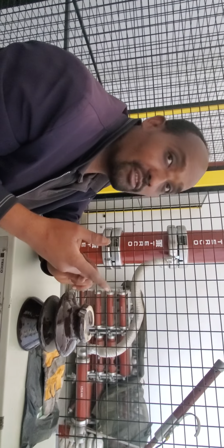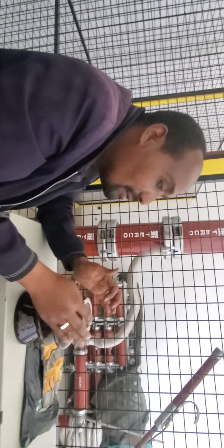Yeah. This implies that there is what? A breakdown of this solid device. That voltage is called puncture voltage. If you compare flashover voltage with puncture voltage, puncture voltage is much greater than flashover voltage. Flashover means breakdown of the air around this. Puncture means permanently damaging this device. So if this is permanently broken down, the current will circulate from the phase to neutral, directly downward.